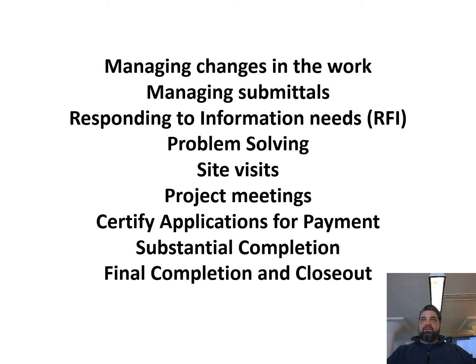So what that means is that the owner buys the building in increments as they go through the project, in monthly increments. And so that invoice will vary in amount because the work in place changes every month. And so when you get the pay app, they'll say, concrete is 75% complete. Your site observations need to be able to confirm, when you go out, yeah, I believe that the contractor is 75% complete with the concrete. And so that's where you balance that out for your owner and the contractor.